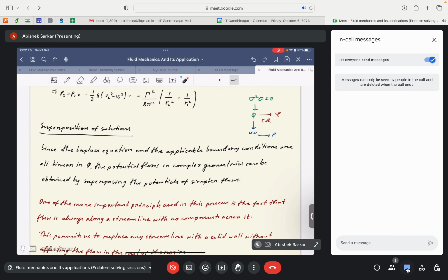So the only part that we need to solve is the linear pressure gradient term. Solve it with respect to a known source term that is composed of the velocity components and its gradients, and just solve the equation, right? So that's how we deal with it, and it's not that complicated. This is the algorithm that we are following. This is very important. This is what we will use throughout our problem solving part. We will find phi, determine U and V. From phi we determine psi. That's the algorithm. It's very simple.